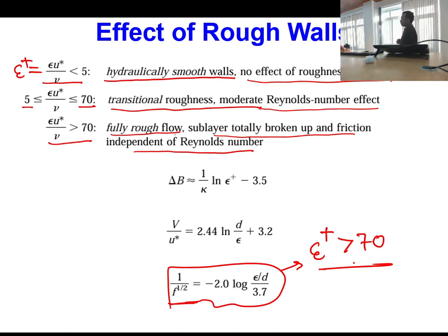It was later found that for a certain range of roughness, particularly near the transitional regime, these coarse sand grains do not mimic surface roughness values equivalent to those of industrial pipes.